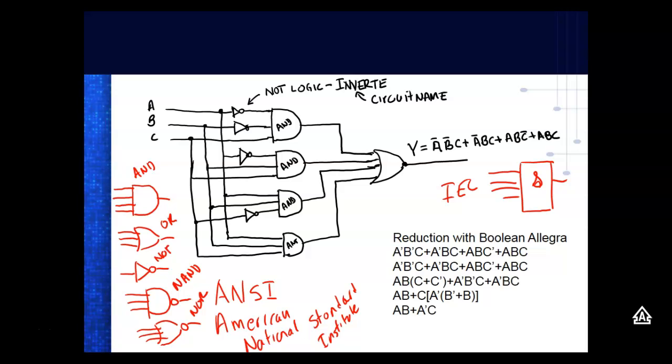We can't do that in RS Logic. The only programming language that RS Logic 500 supports is ladder. The Studio 5000 supports ladder. It supports function block programming. It supports function diagram programming and structured text. So what it does, it gives a route for people. So originally PLCs were for electricians. They understood the ladder logic. That's the way we want to program, right? It would be real easy for them to adopt that.